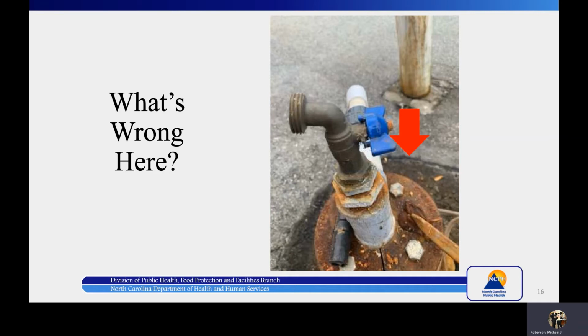If you see, the asphalt around that well looks quite damp in comparison to the asphalt in the general parking lot. So these are all potential areas where water can get trapped underneath that asphalt and siphon towards that well and contaminate the water supply. You can also see that the wire opening probably needs to be recaulked as well. So there are several things that this wellhead needs in order to be brought back into compliance with the 1700 rule.